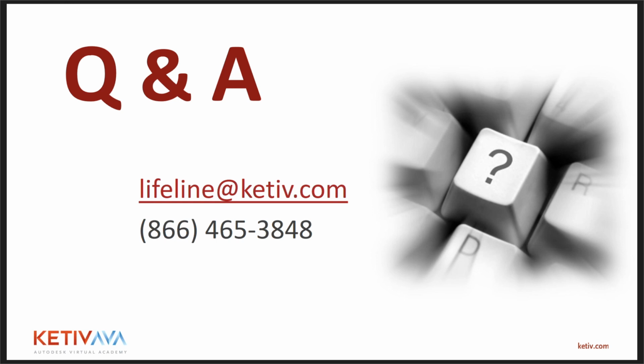So if you need to know how to load custom materials, it is grabbing from the Inventor material library too. We do have an AVA on how to use that library and manipulate it, add your own things. If you're interested in that, let us know or look it up on our YouTube channel: materials library Inventor. You'll be able to find that particular video. All of those materials do carry over to Nastran. You can honestly make whatever you want in terms of material if you know what your material properties are for that particular material.